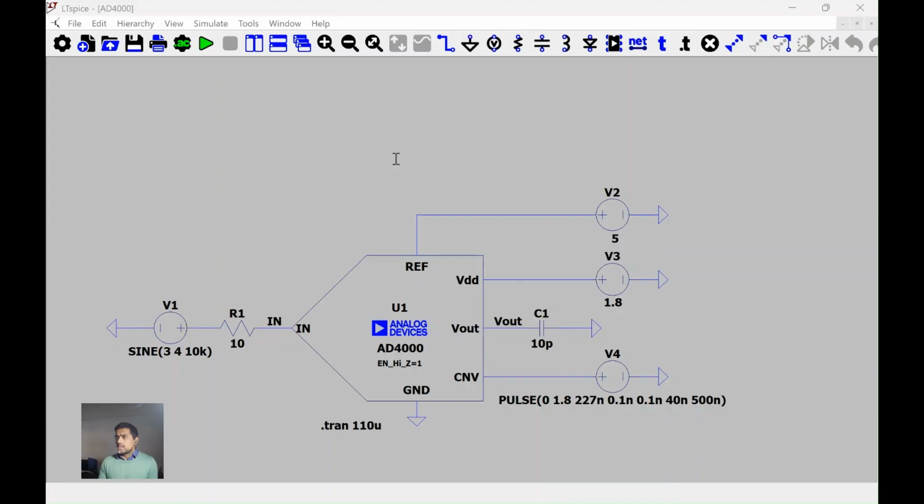In this example, we've taken a small circuit of an ADC, which has about 8 components. It might be easy to manually enter 8 components into SLIKWORKS and then do the FMEDA. But imagine if you had a bigger circuit where there are 200 components. It does not make sense to manually enter all of them into the FMEDA. So there has to be a better way to import files. And here, using the Spice netlist is a very good way to import the file.